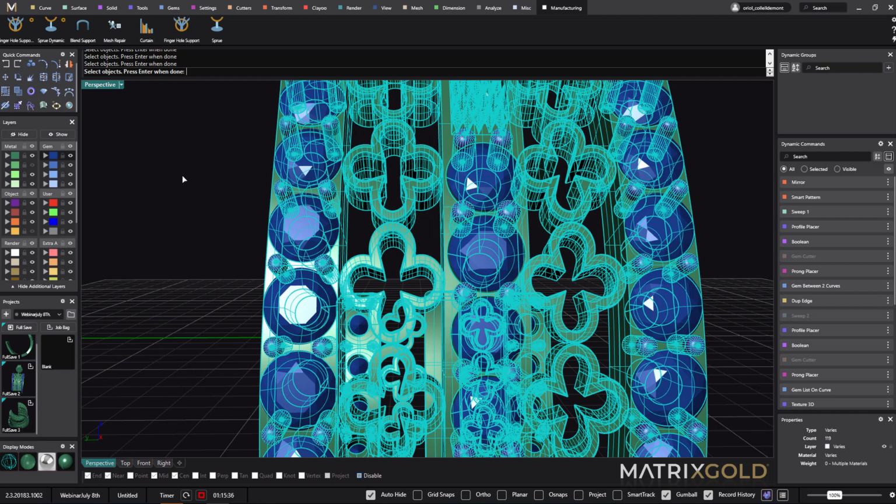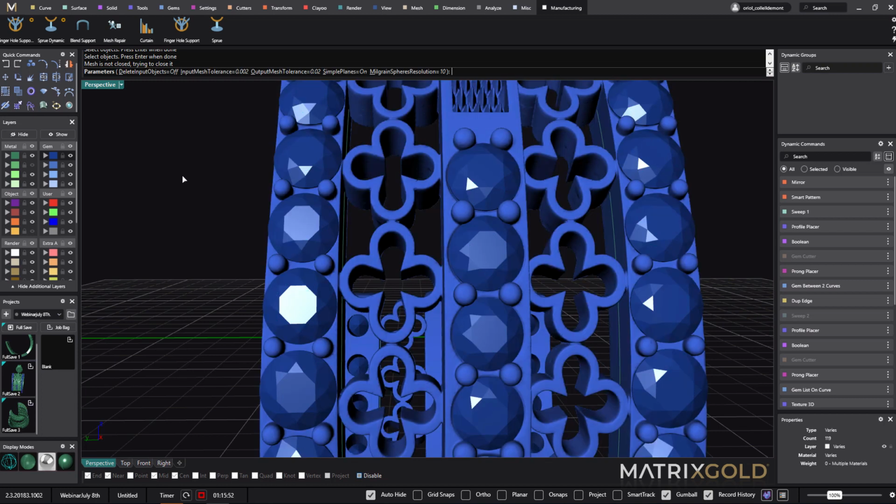So now what the mesh repair is doing is trying to find out if there is any hole. If there is any hole, it's trying to fix it and cap it, and then you will see how we get in blue a result from this mesh. Now we have this in blue, and here is where you see the settings that I was telling you.